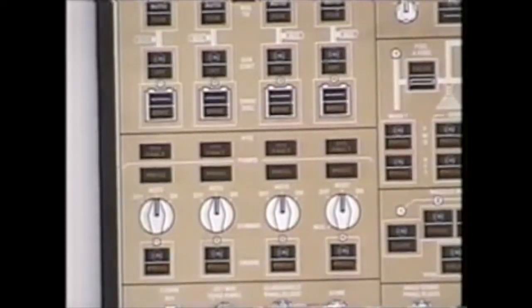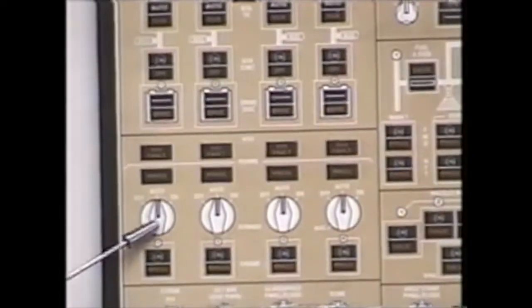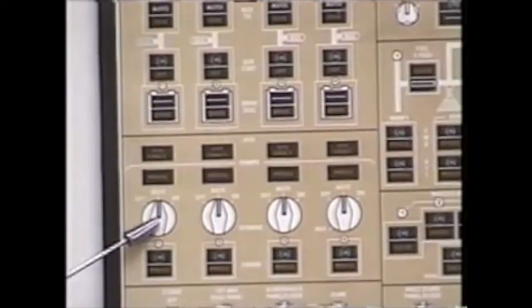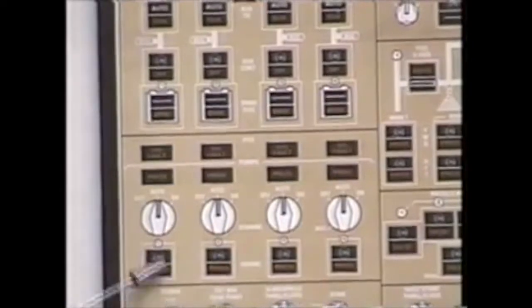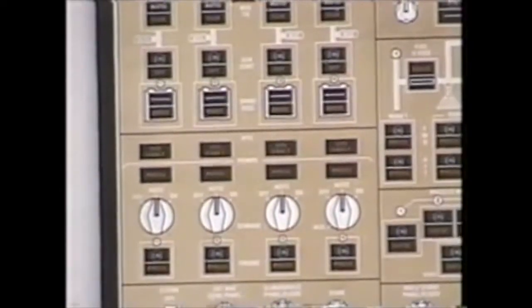It is not putting out system pressure, but it is getting lubrication for cooling. If we pull the fire switch for that engine, that will shut off the fluid supply to the EDP and not the ADP. As a result, the hydraulic system will still operate. The air demand pump takes pneumatic air from another point of your airplane, not the engine. We'll pressurize the system. The fluid supply is shut off to the EDP. As a result, the pump is not putting out pressure, and it is no longer getting lubrication for cooling. However, if the engine is windmilling, the EDP is still turning.